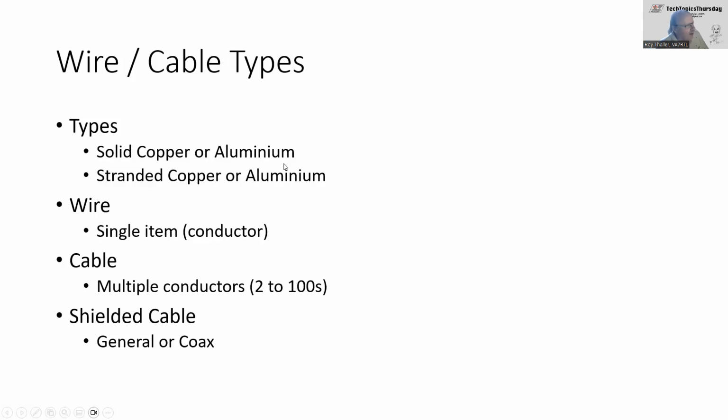If you have aluminum wiring, it's best not to touch it. But if you start hooking things up to it, then you can get chemical reactions between the copper and the aluminum. You can get special sleeves to put on the aluminum that help with that. But it can be a fire hazard, so that's why they've stopped in general using aluminum. It tends to be a little bit lighter in weight and maybe less expensive than copper.